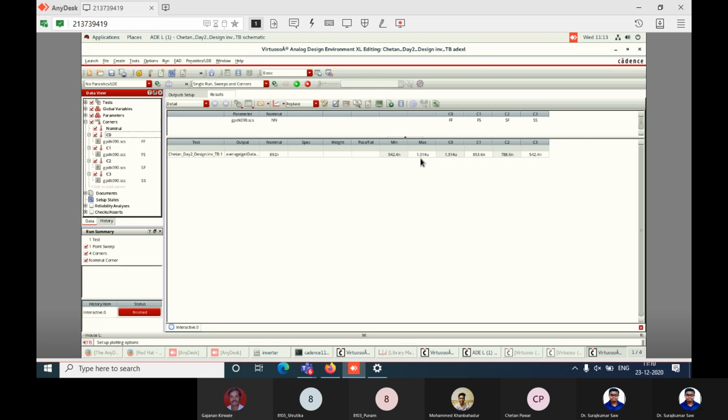Now, from your side, I want you to go to ADE and load the equation of delay. From there you can again go to the ADEXL window and check for the 4 different corners how the delay is changing. This one I have shown you for power. Just go for delay. Sir, please explain.